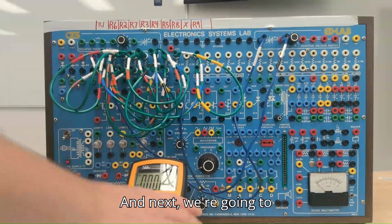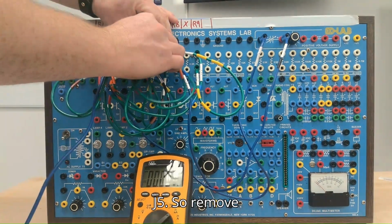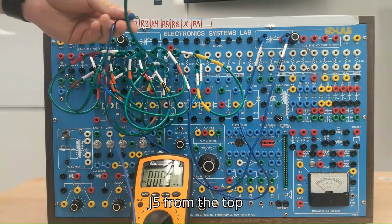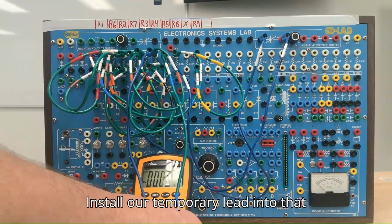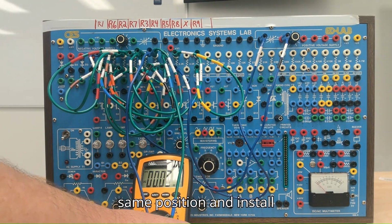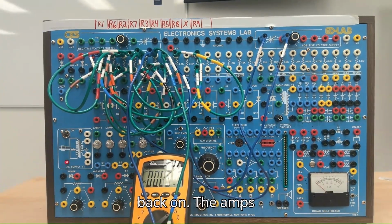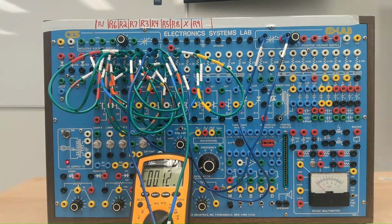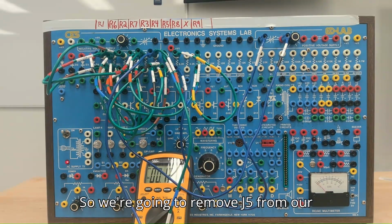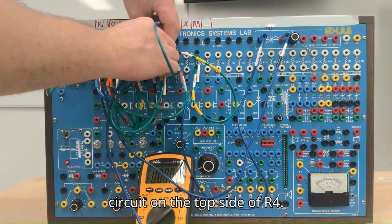And next, we're going to measure the amperage flowing through J5. So remove J5 from the top side of R4. Install our temporary lead into that same position and install J5 into our meter. Turn our unit back on. The amps flowing through J5, 0.12 milliamps. So we're going to remove J5 from our meter and install it back into our circuit on the top side of R4.